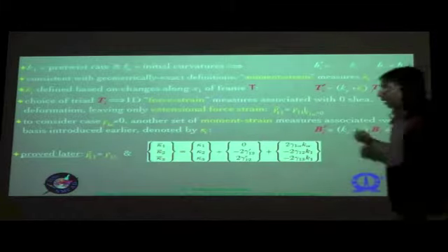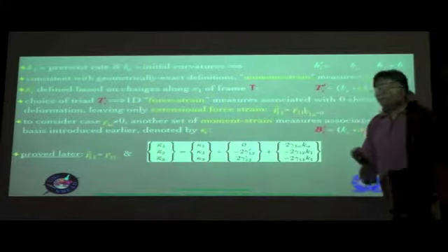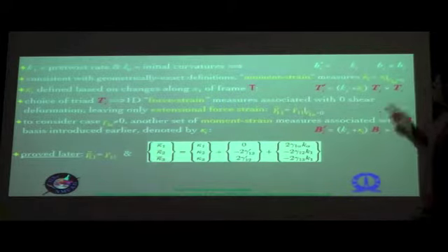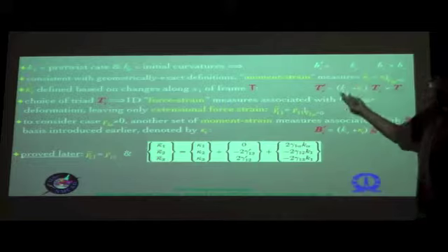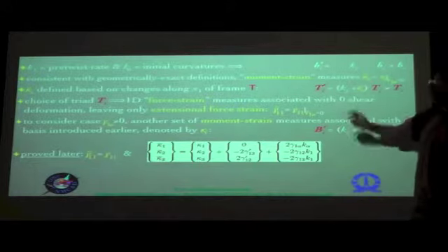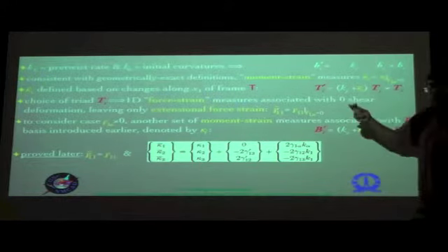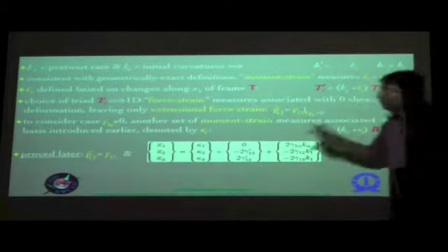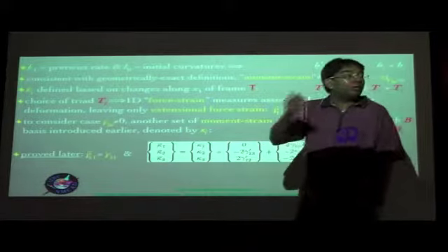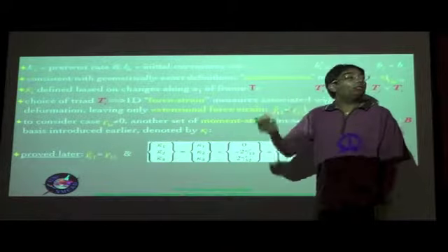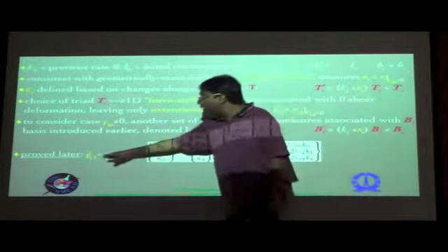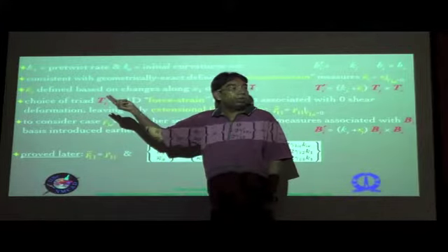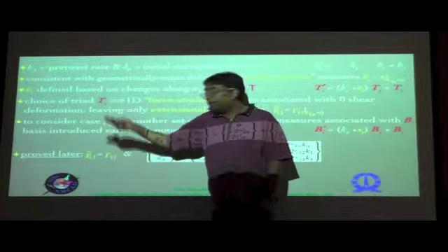And it can be proved by the geometry, and you can see that in the textbook as well, that in all general cases, whatever the general deformations might be and whatever the variables which are non-zero, even though gamma 11 bar is defined as gamma 11 when 2 gamma 1 alpha are set equal to 0, even when they are not 0, it turns out that you can prove that gamma 11 bar is nothing but the same as the gamma 11 that you used in the previous example.